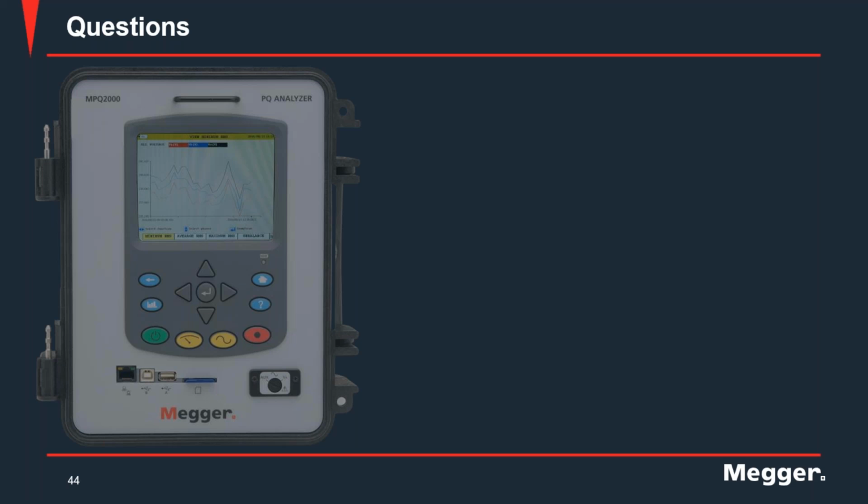But when you're seeing a DC overvoltage, one thing to keep in mind is that the DC bus is going to be generated from AC rectifiers. So the first thing to look at is that, depending on the design of the AC rectifier, the voltage you get on that bus is going to be about 35% higher. If you have a 3-phase rectifier, that voltage will be about 35% higher than the RMS voltage coming into the rectifier. So you'll automatically see that. But I see in the question that you've also tapped down, and that really hasn't helped the problem.